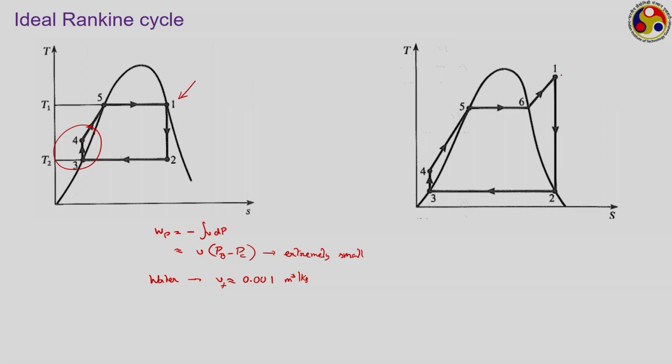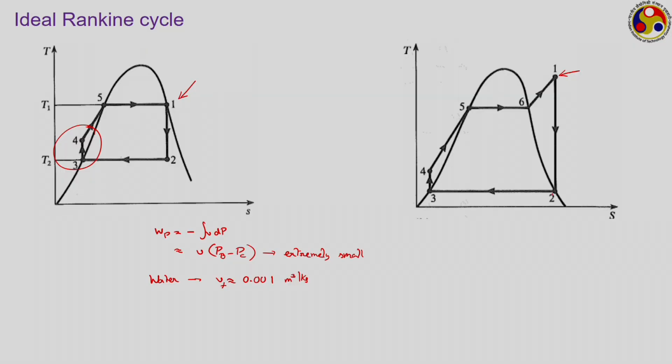In the second case, at the entry to the turbine, the state of the working medium is that of superheated vapor. So, the entire expansion can be done entirely on the vapor side, as shown in this particular diagram, starting from superheated vapor to saturated vapor, or sometimes we may have it expanded a bit more into a mixture zone coming somewhere here, that is, the major part done in the superheated vapor side and only a small portion in the mixture side.